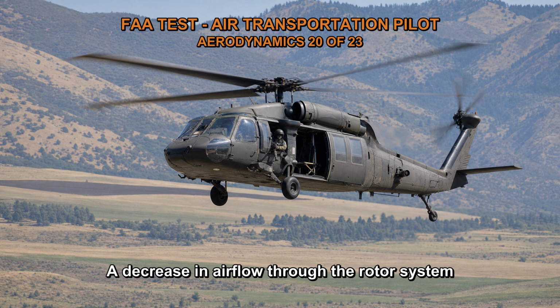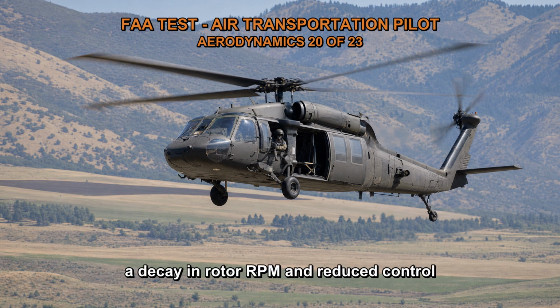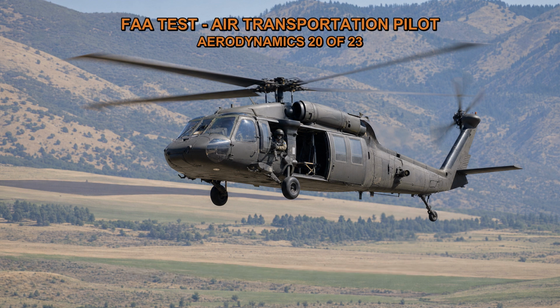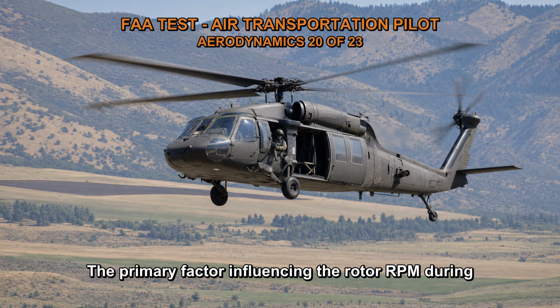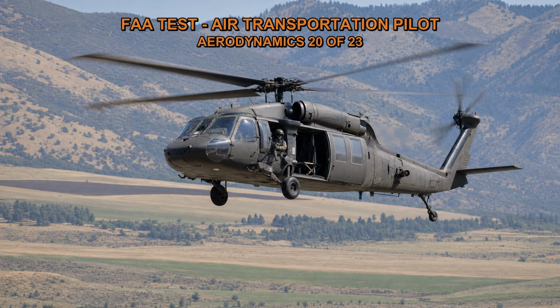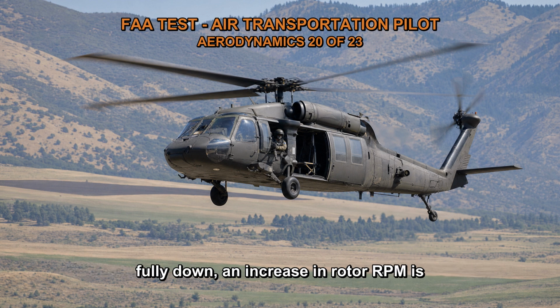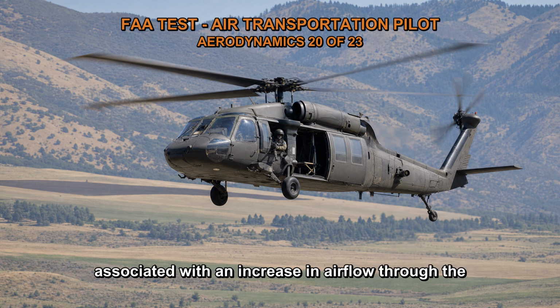A decrease in airflow through the rotor system would have the opposite effect, potentially leading to a decay in rotor RPM and reduced control effectiveness. A decrease in airspeed can be a consequence of the autorotation, but it is not directly associated with an increase in rotor RPM. The primary factor influencing the rotor RPM during an autorotation is the airflow through the rotor system. Therefore, during an autorotation with the collective pitch fully down, an increase in rotor RPM is associated with an increase in airflow through the rotor system.